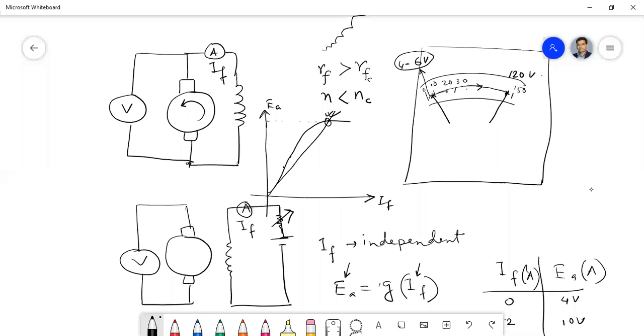Now in a separately excited machine, all these points are defined and stable because you can get all these points individually. That means you will get the same curve as in case of separately excited generator, but in the shunt case you cannot trace the curve; you won't get any point except this one. Now is the point clear?